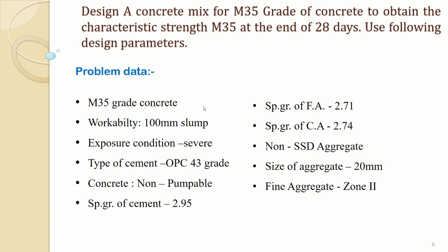Now we will go for the actual problem. Here I have intentionally taken a problem of M35 grade of concrete. It is often asked or often needed in the field also. So here M35 grade of concrete is proposed. Workability required is 100 mm slump. Exposure condition I have taken as severe, and cement is OPC 43 grade.